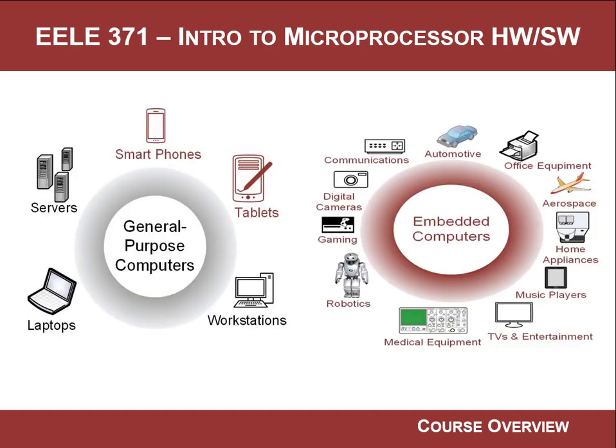So what we do when we learn to understand computer hardware is we start learning about embedded computers because they're a little simpler. It's still the same concept as a regular or general purpose computer in that it has a CPU, central processing unit, that can execute a set of instructions. It has program memory, where you put the instructions in a particular order to implement an algorithm in order to accomplish a task. It has data memory, which is used for temporary storage, and then it has I/O to get the information to the outside world. All computers have that, okay? It's just that general purpose computers tend to be a lot bigger and have a lot more hardware resources to support an operating system, while embedded computers do not.